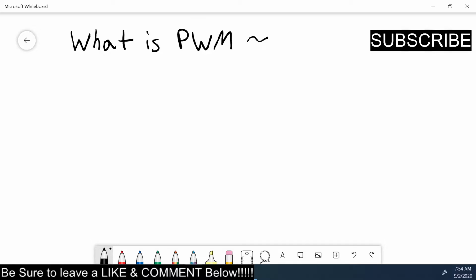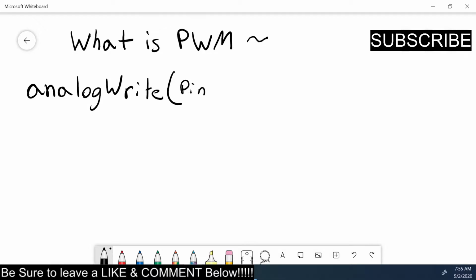Well, you can do a function called analogWrite, with a capital W. You write your pin location, which will be a digital pin, and then you can set it to a value between 0 and 255.